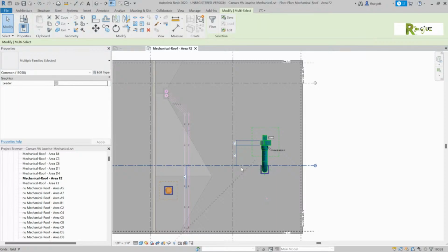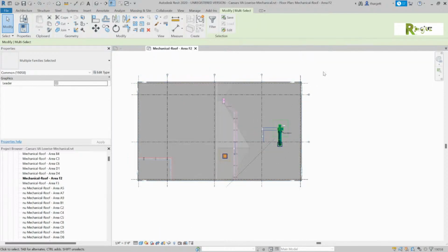And I have known people who deleted those 19,000 dimensions, and it's usually late in the project, and it's not a good day. It's a real hard one to explain to the bosses. So be wary of that. If you did a window around your view, I don't care, just grab a bunch of stuff.